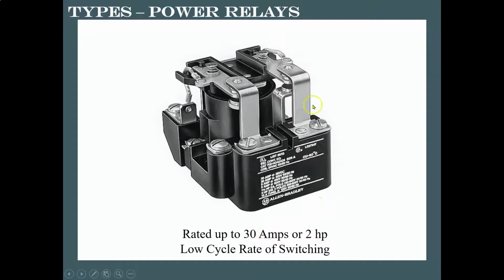Right. One problem with these guys is they are fully exposed. Right. So you have that. There's your armature right here, and your contacts. If you have 30 amps traveling through, this is all exposed, which means if you touch that, you got 30 amps going through you now potentially. So not on the safer side, but they still work.